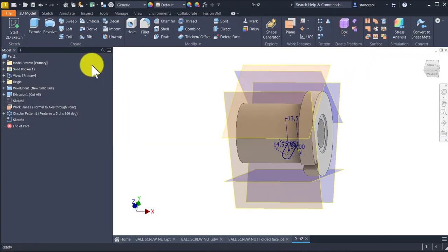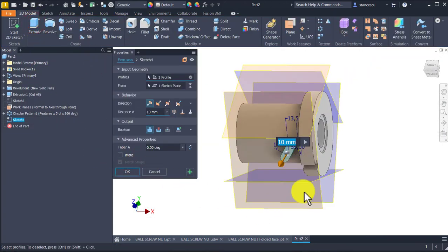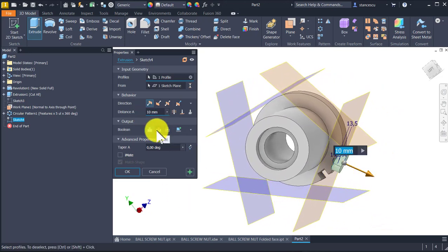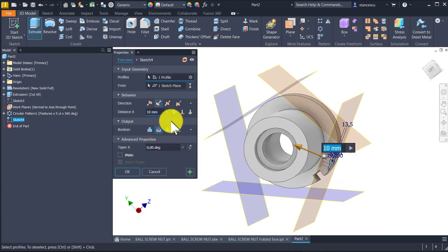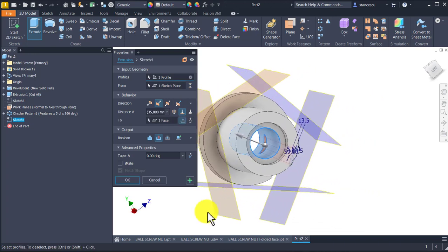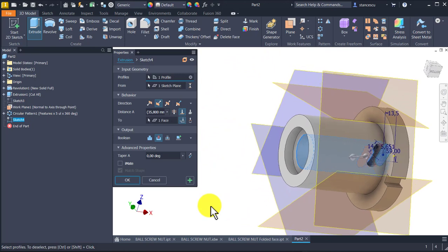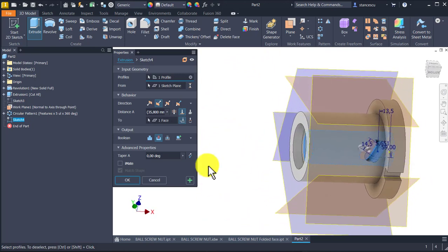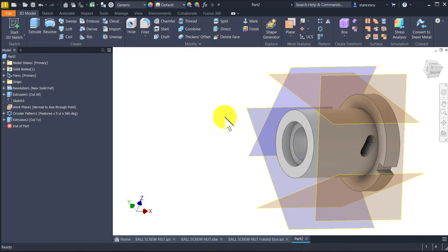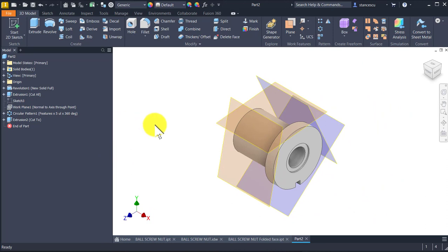Finish sketch, extrude, not join but cut, the other direction to the inside cylinder, so that we obtain a slot in the object. Since I used this plane, I hide it. Yes, we have a system, a procedure.